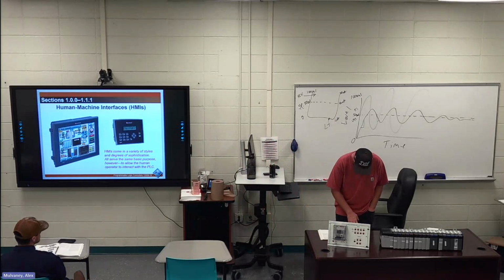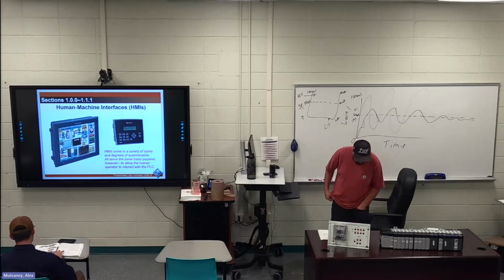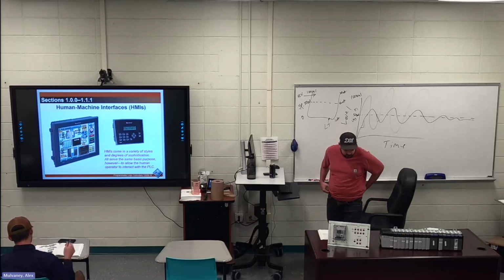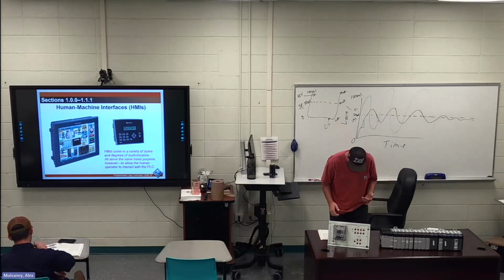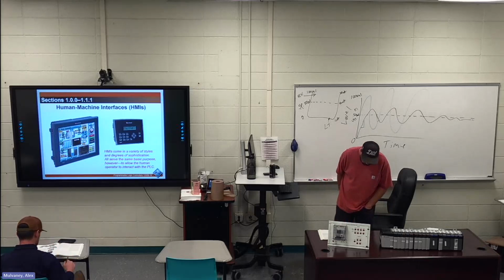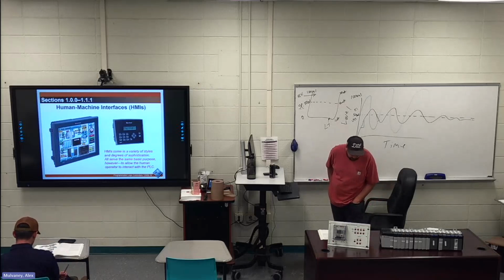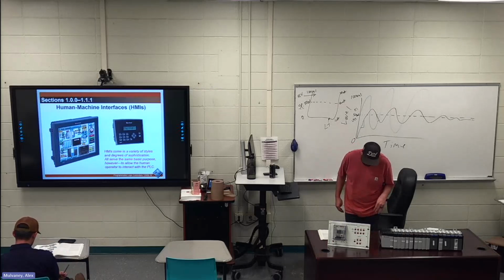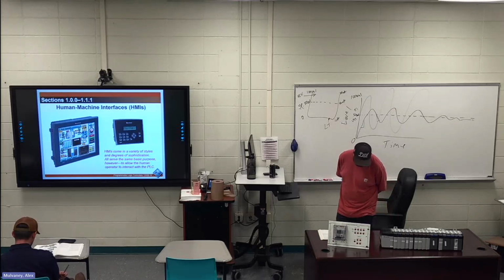Guess what? The next paragraph's highlighted. 120, hardwired systems versus PLC systems. So I'm going to give you the highlights and talk about it. The whole paragraph's highlighted. First sentence is one highlight, the rest is another. The primary hardwired components of a PLC are the power supply, the processor, I/O modules, and the communication modules. A personal computer is often used to program the processor, but this is not considered a primary component because once the processor is programmed, the computer is disconnected.